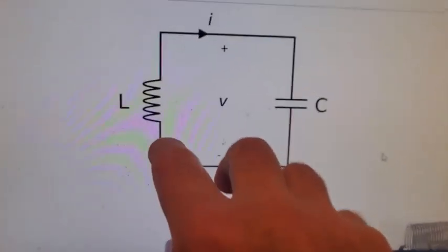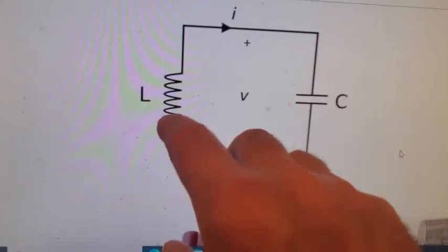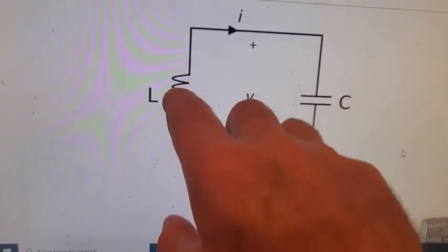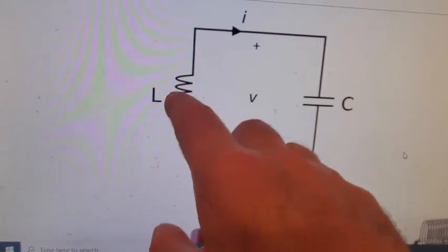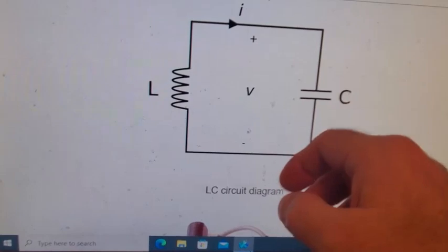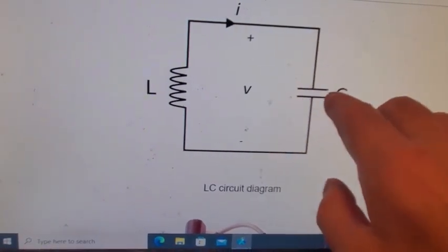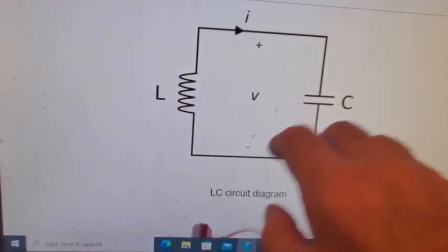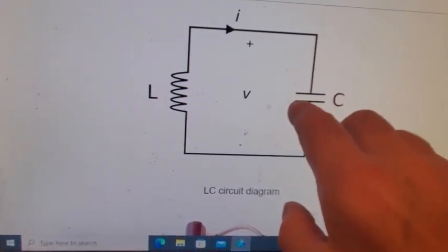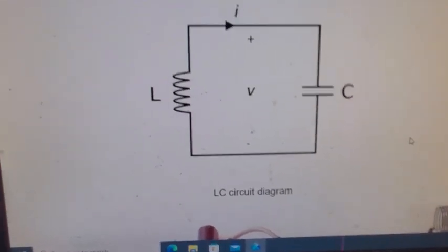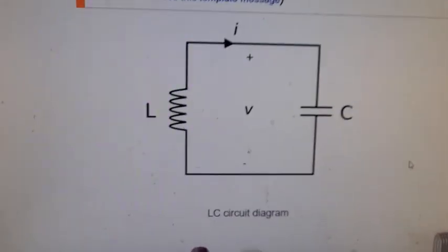So we have this situation where the capacitor discharges, the energy ends up in the inductor. When the magnetic field strength of the inductor changes, then energy is shot back the other way. The capacitor charges negatively, and the process goes on again at a specific frequency. And how quickly that dampens out is determined by Q factor.